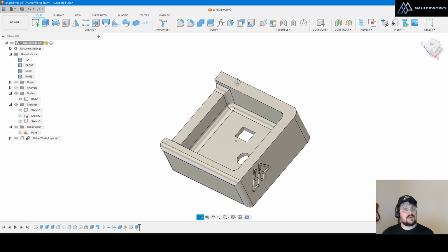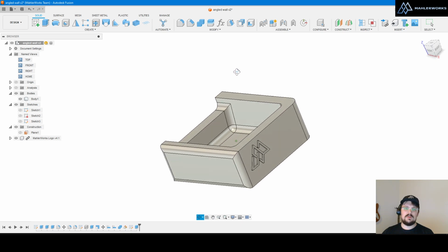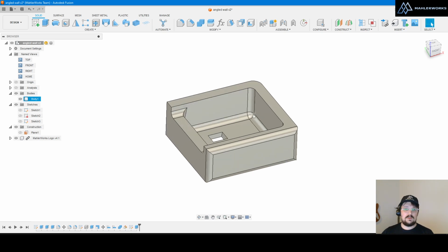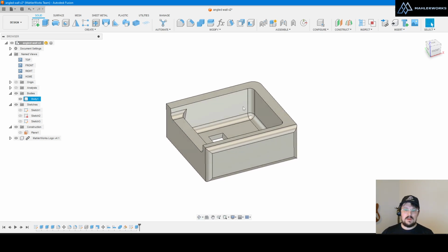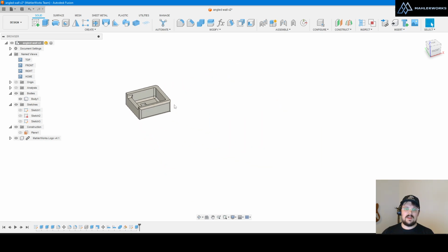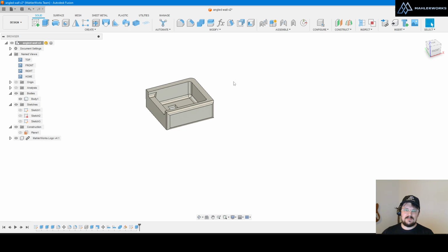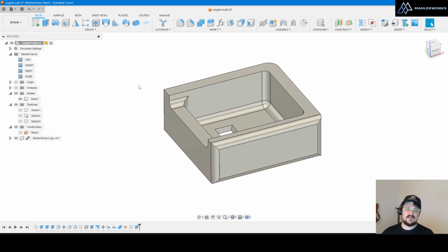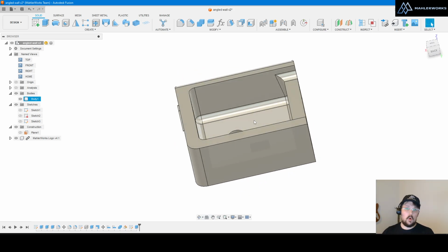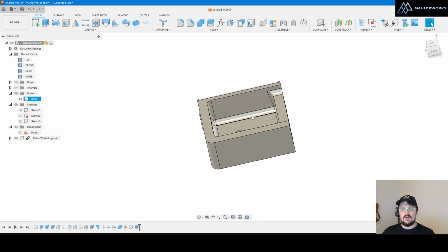And if I click down on that scroll wheel, I get the ability to orbit. Now, this is what I use most commonly. Almost always, I am either zooming out, zooming in, and based on where I have my mouse, I'm zooming in or out to where my cursor is, and that's how I orient around a part.